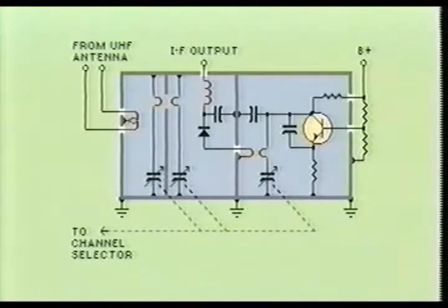The tuned line and the series trimmer capacitor form a tuned resonant circuit. This is the first part of the channel selection circuitry. The selected RF signal is then passed through the window which separates compartment 1 from compartment 2. From here, the signal is electromagnetically coupled to the mixer tuned line coil.